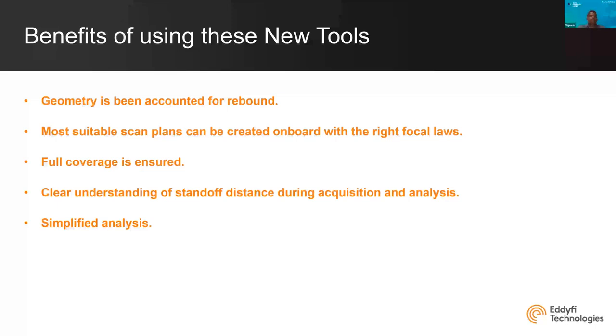The software is inbuilt in the equipment, and you can prepare the complete setup from the same equipment that you're going to use in the field to do this inspection. We can also make sure of 100% coverage, that the weld is completely inspected, by positioning the probe at different areas and simulating the scenarios that would come and how the ultrasonic energy is going to propagate into the weld.